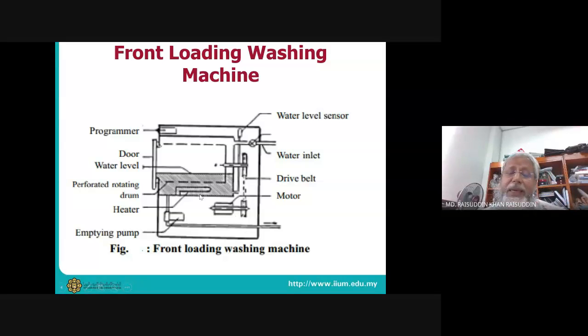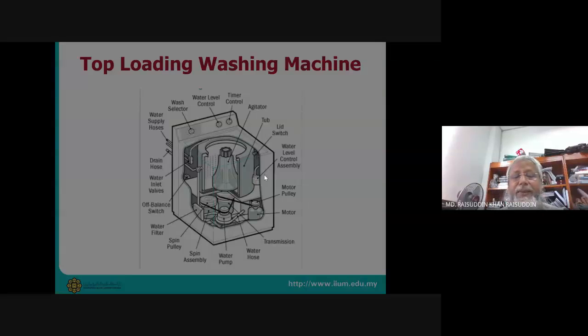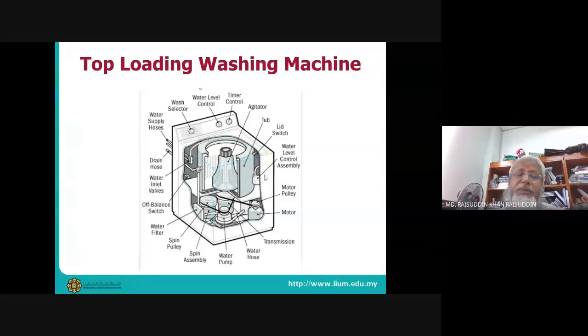And second, when you have big load issues where the output can stop, we put in this belt drive so that the motor cannot stall. Otherwise, if for some reason the drum is overloaded and you want to drive the motor and it doesn't move, the motor may burn. But if you have a belt and pulley system, if it doesn't move, it will just slip and the belt will burn.